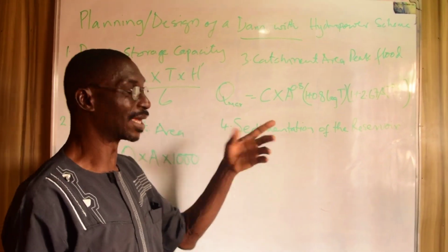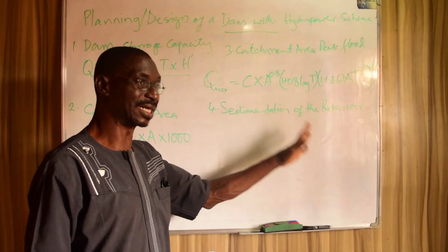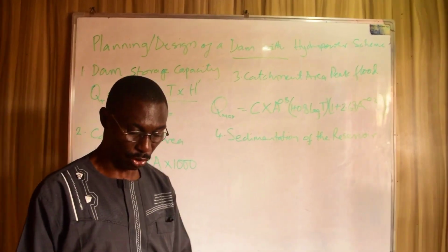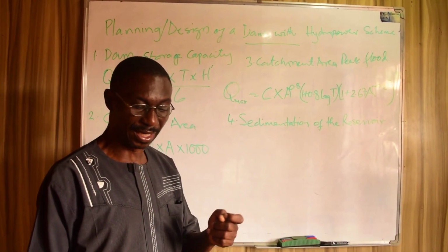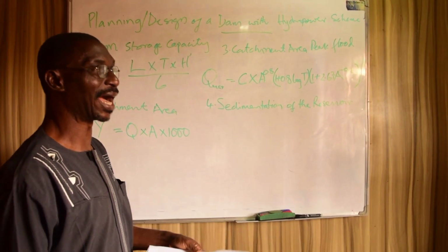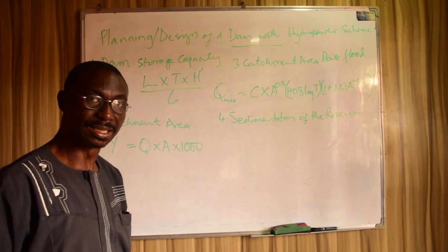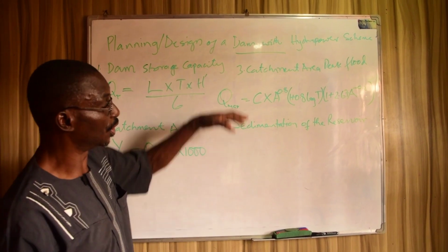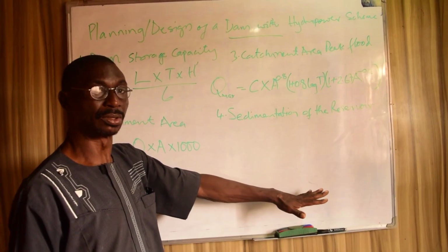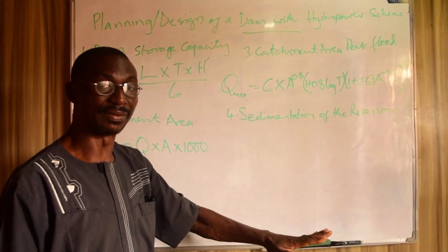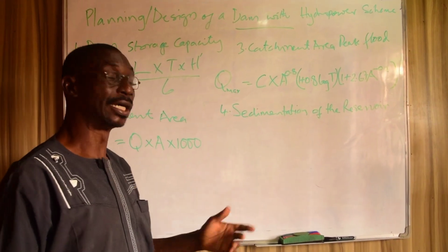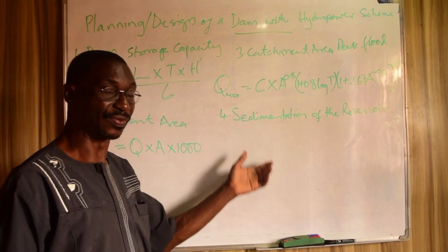So how do you take care of it? You must note that when there is sedimentation, you must do the cleaning. You remove the sediments and so on and so forth, which is very, very important. Because when there are flows coming, they are carrying sediments, debris, sand, all whatnots into the reservoir itself. And in this reservoir they will settle, silt and whatever. That reduces the storage capacity of the reservoir. So it's very, very important.